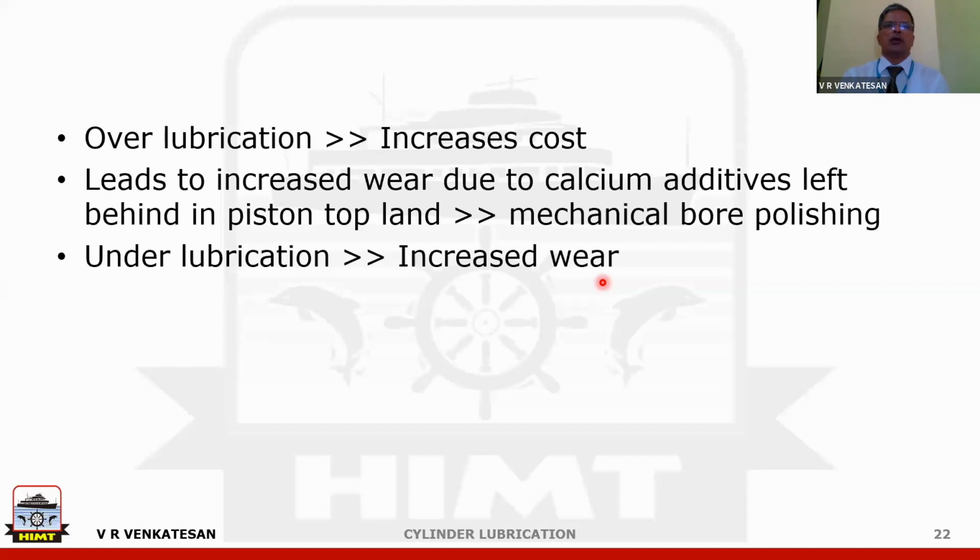But there are some drawbacks in the under piston inspection. It is because when do you do the inspection? It is after you finish your voyage, after you have maneuvered and you stop the engine. So during maneuvering, is the cylinder lubrication increased in every vessel? Yes, sir. Automatically it goes up. It is always increased. Yes. So that is because of the starting and stopping and running at low speed.